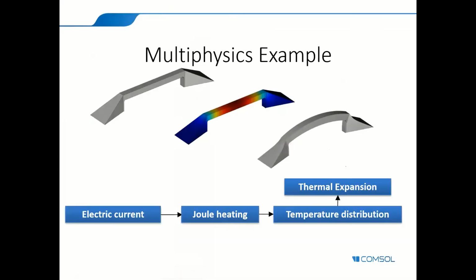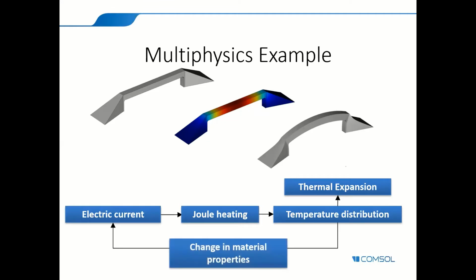An example for this is this small micro resistor, where you have a micro resistor beam between two supports. An electrical current passes through the system, which induces a Joule heating effect and it starts heating up. The material starts extending and buckling because it's stuck between two supports. When we add the fully coupled system, because this was a one-way coupled system, we get this effect.